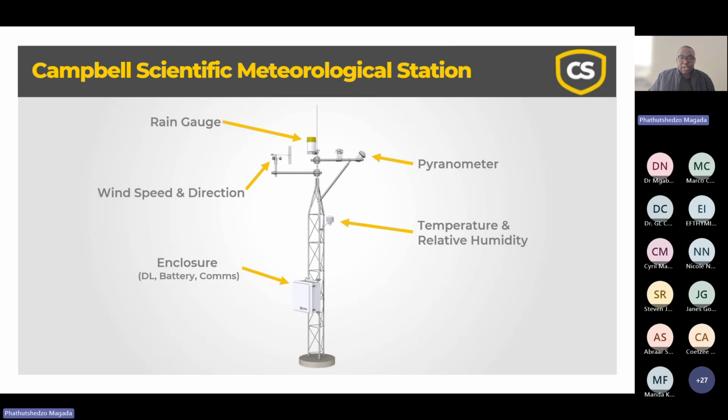The important aspect is how this meteorological station has impact in dam monitoring. For example, real-time meteorological data are necessary to check rainfall intensity and duration, which are fed into rainfall runoff models to calculate expected reservoir inflow.